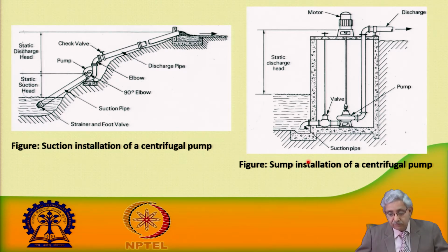Now, when we talk of the water level being quite deep, then the pump is kept near the water surface. That we call a sump installation, and the motor is on the ground level. So, the delivery head increases, meaning the total head, when we are talking of static discharge head.